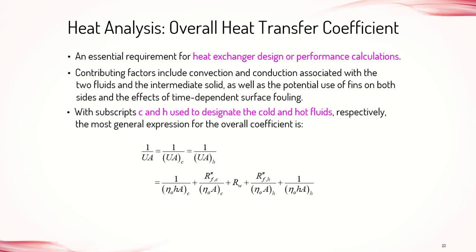In order for us to design or calculate the performance of that heat exchanger, we are going to use heat analysis, and the contributing factors include convection and conduction associated with the two fluids and intermediate solids, as well as the potential use of fins on both sides and the effect of time-dependent surface fouling. These are the parameters that we take into consideration to do the heat analysis of a heat exchanger.